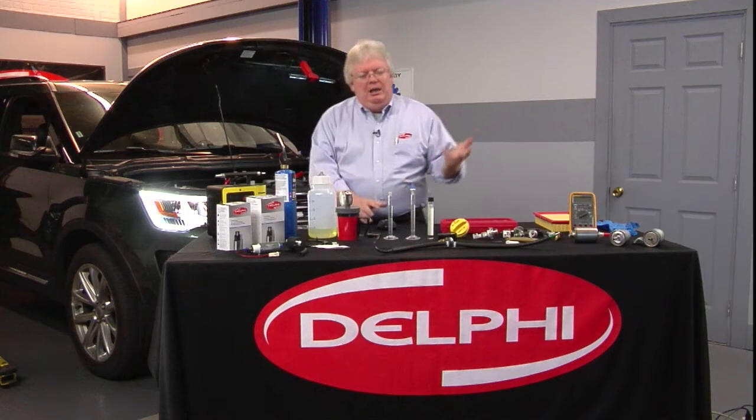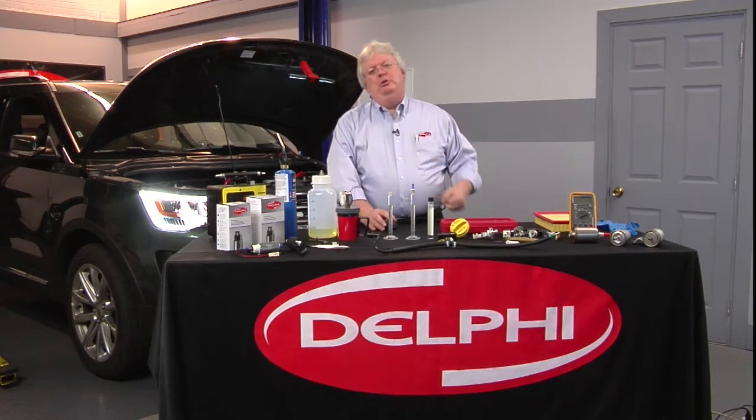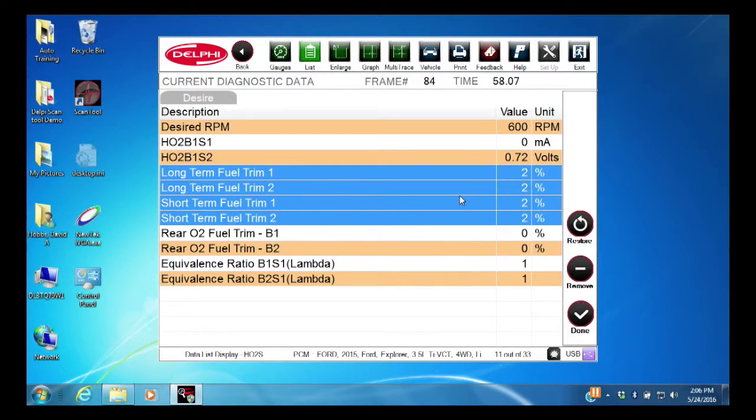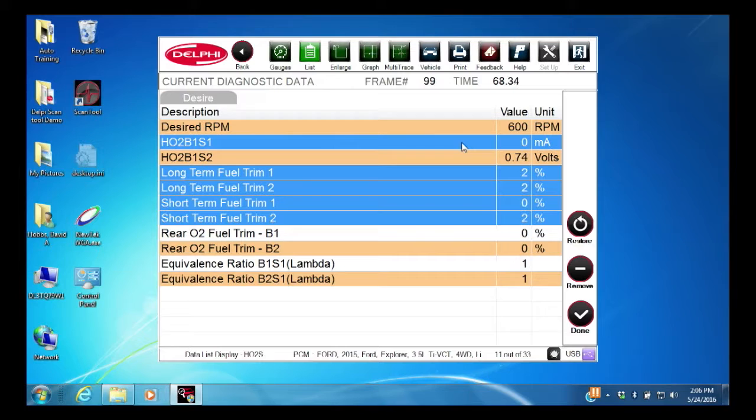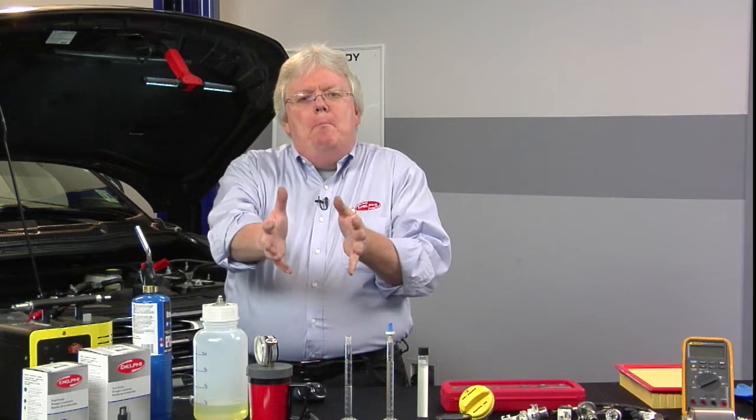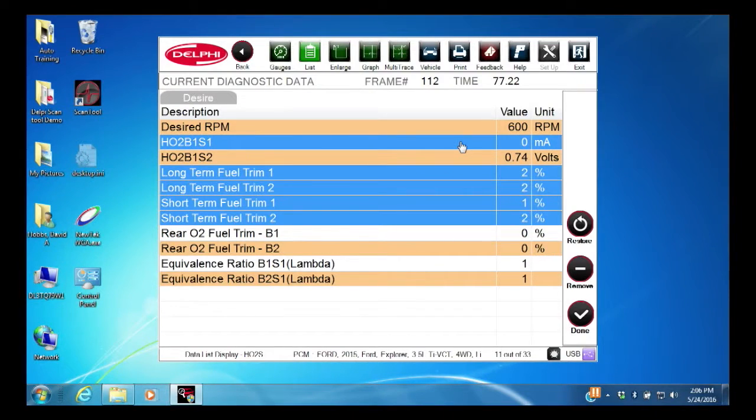I'm seeing a lot of O2 left over, or no O2 left over. So very little change, very little correction, and we've got a nice low RPM, 600 RPMs. That O2 sensor, a wide range sensor reading before the cat on bank 1, is reading 0 milliamps. So we're not putting much current in there to make the O2 sensor respond to a rich or lean mixture to get that wide range of air fuel. So that's pretty much normal.